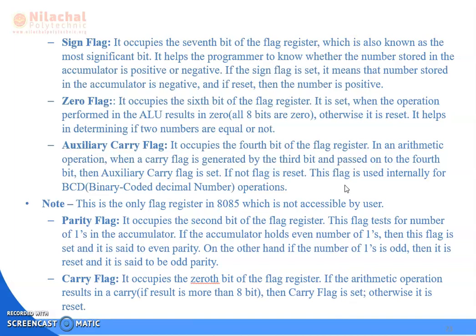Next, the carry flag. What is the carry flag? It occupies the 0th bit of the flag register. If the arithmetic operation results in a carry, that is, if the result is more than 8 bits, then the carry flag is set, otherwise it is reset.